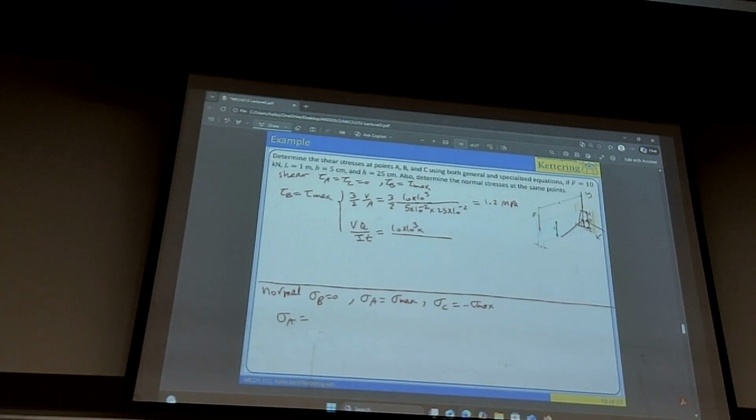If I go X, Y, Z, Z is not drawn well, it's like this. So we see that it's curling around which axis, guys? The bending is about which axis? X. Very good. Bending downward about X. So the real I is I about X.